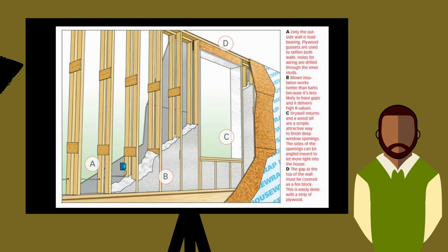Then when the plywood comes, you got a huge problem, or not a huge problem, but you're gonna have to buy some material just to make sure you got plywood to nail, or you got some studs to nail plywood to.